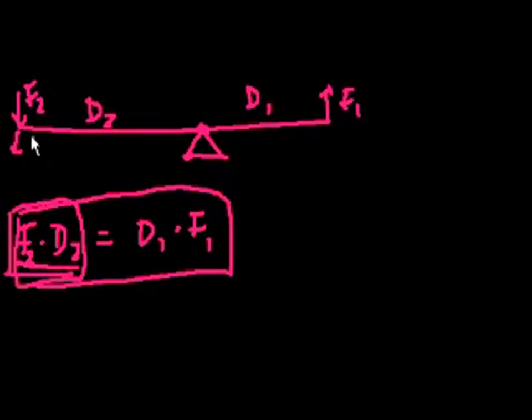I know the relationship between the two forces I'm applying. The input force, so actually I shouldn't call this force 2, I should call this input force. But anyway, the input force times the distance from the input force to the fulcrum is equal to the output force times the distance from the output force to the fulcrum.